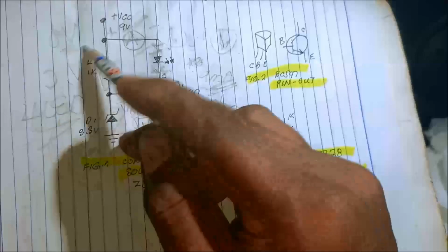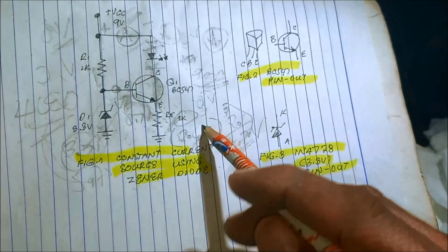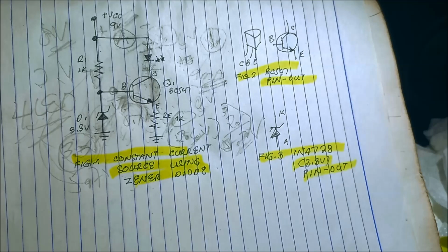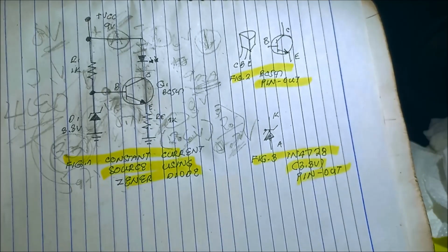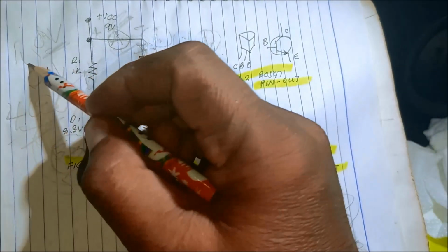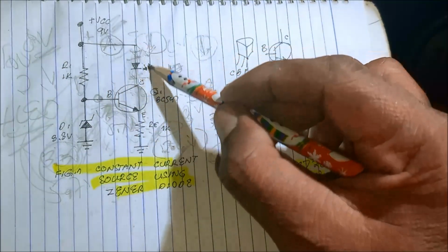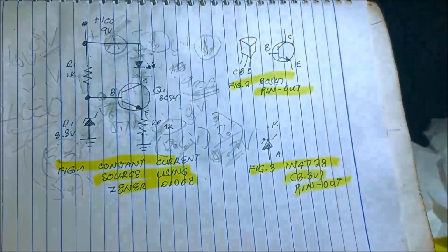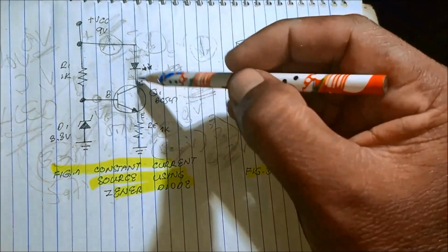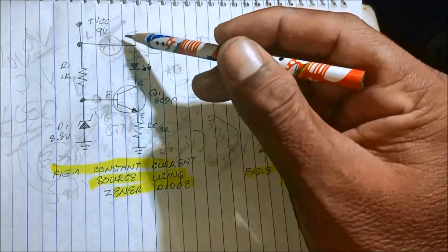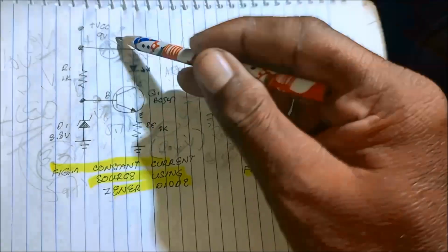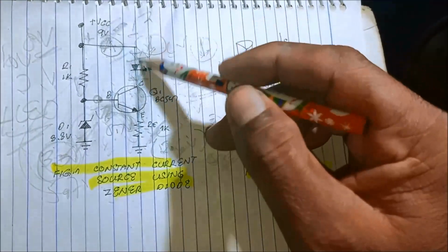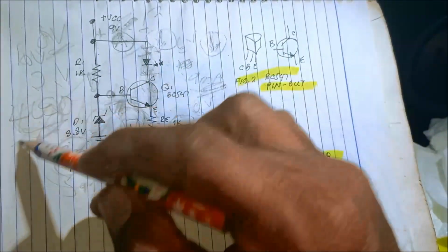The 4 LEDs equal 8 volts plus the 2 volts at the emitter, which is constant, making this 10 volts, which is not enough to turn on the LEDs because our supply is 9 volts. So we had better vary the supply, making it at least 12 volts, in order to turn on these 4 LEDs.